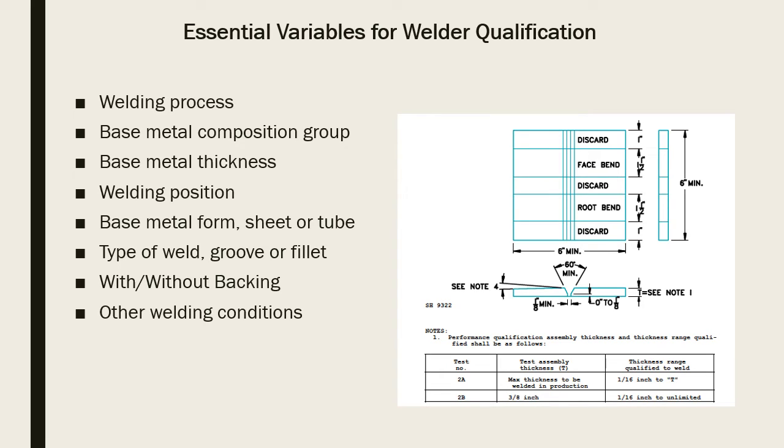Maybe it's with a shielding gas or whatever. Depends on which code and customer requirements and all that. But basically, when you're qualifying a welder, these are the things you're worried about. When you're qualifying a procedure, there's 20 different things that you need to address. Generally, for welder qualification, this is it. You qualify to these, you look at your essential variables, you're good. And that qualifies a guy to weld using any number of different welding procedures as long as they meet these criteria, these essential variables.